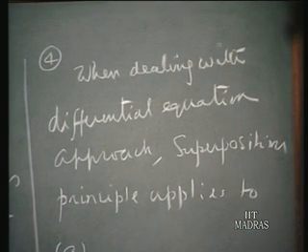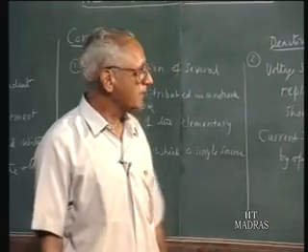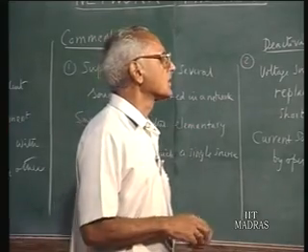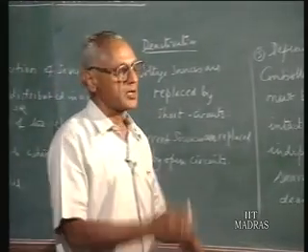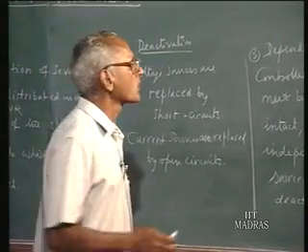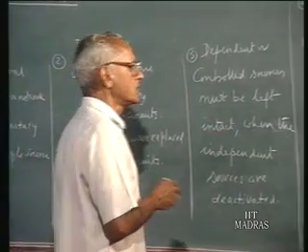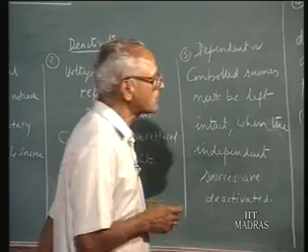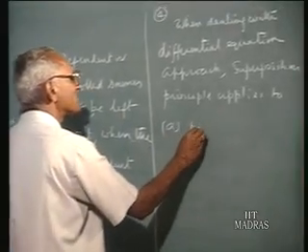Suppose you are taking up the differential equation approach to the solution of a network problem, and then you have several sources and you consider one source at a time, then you would like to find out the response due to each source in turn. Then you can superpose the responses to the individual sources, provided the response that you are talking about is a particular integral solution.